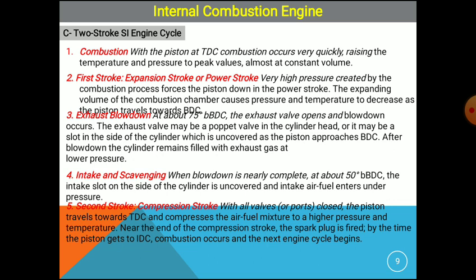Similarly, the intake and scavenging: when blowdown is nearly complete, at about 50 degrees of the crankshaft position at the bottom right side, the intake slot on the side of the cylinder is uncovered, and the intake air-fuel mixture enters under pressure. The second stroke is the compression stroke, with all valves or ports, that is both intake and exhaust, closed.